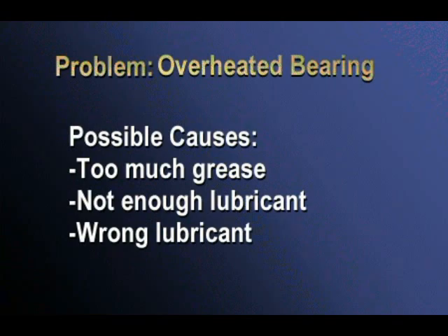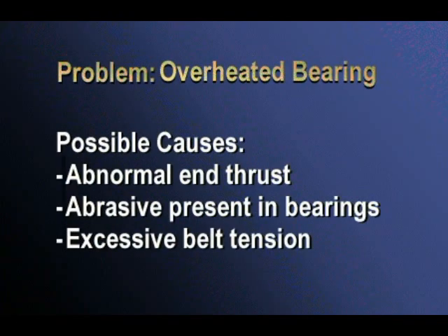Problem: overheated bearing. Possible causes: there is too much grease in the ball bearing, or insufficient oil, or the wrong type of lubricant is used. There is abnormal end thrust. There is dirt in the bearings. There is excessive belt tension.